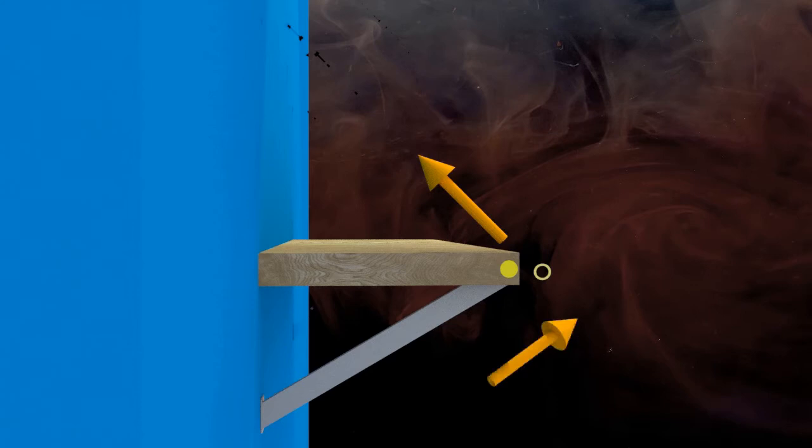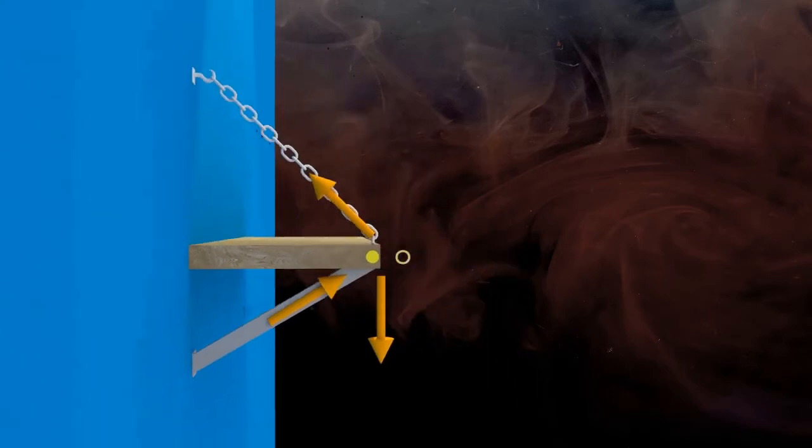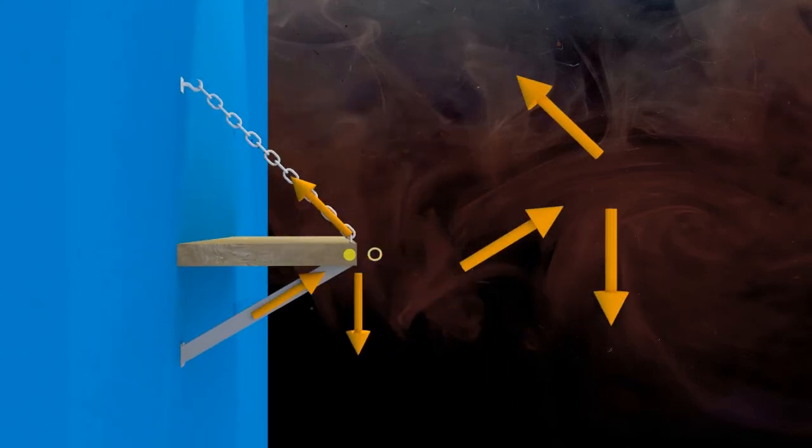So reaction will be in the opposite direction, and again it is acting along the bracket. Additionally, force F is acting in downward direction due to self weight of the shelf and weight of objects placed on the shelf. And this is the free body diagram of the bracket along x and y axis.